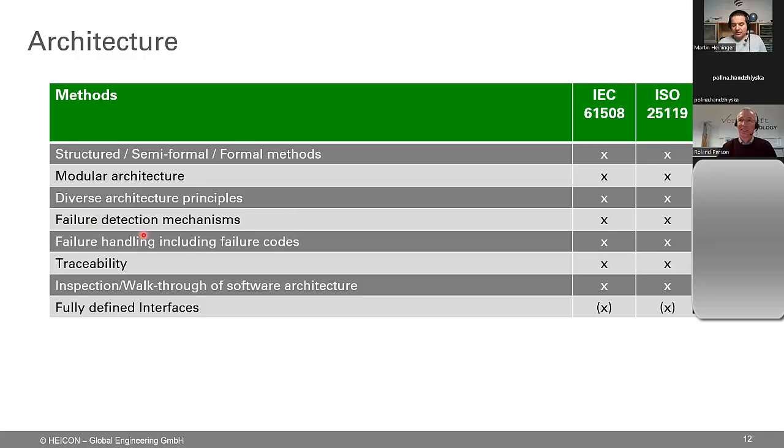Externals to your control unit might be some sensor failures or from some other systems which you have to handle. Internal failures are when the hardware is breaking, and all the architecture mechanisms, the failure mechanisms you need, you derive when you do your architecture from the FMEDA. So there is some safety mechanism. You've seen in my very first slide or second slide how I separate functional safety, with system engineering and the safety engineering which does a FMEDA, and the results of it feed into the architecture of your system software.